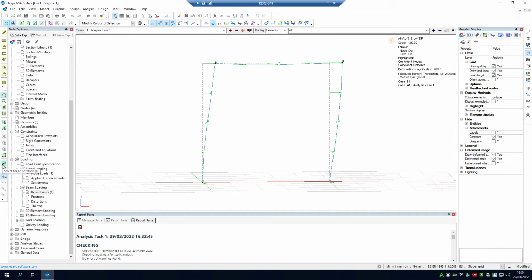We go over here, back to the annotation button. Highlight. If I just highlight this beam here, it will give me the deflection values. These are in millimeters, by the way. You can tell because the magnification shows it barely budges. Whereas this is a 5-meter gap, this is 2.5 millimeters. So you're basically not going to be able to see it. But if I annotate only this beam, it's only going to show me these values. If I annotate the middle of this beam, it's not going to show me anything. You need to get the entire beam in, and then it will annotate that. So we get the entire structure in.